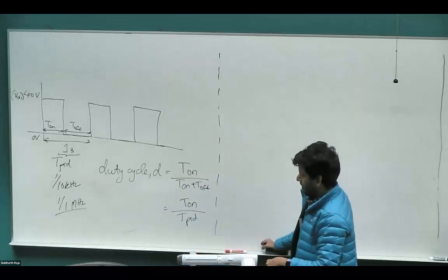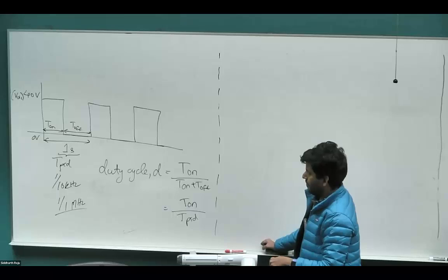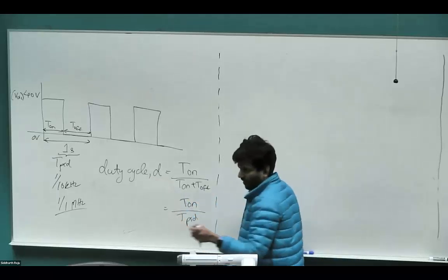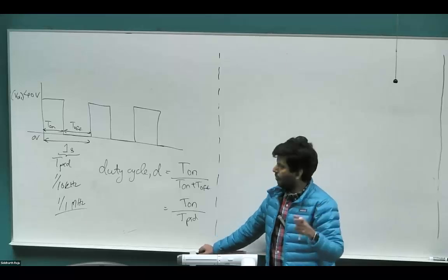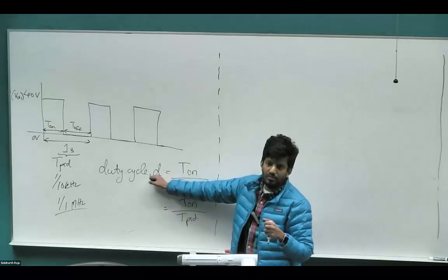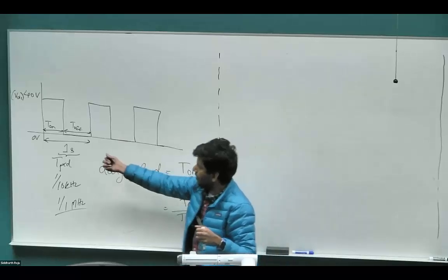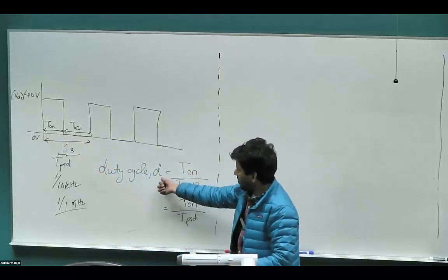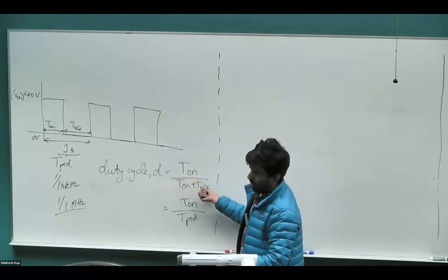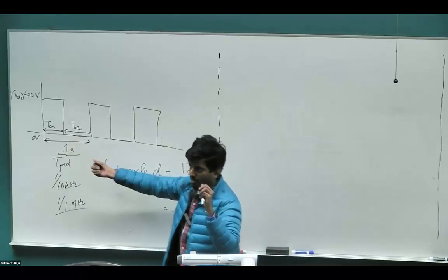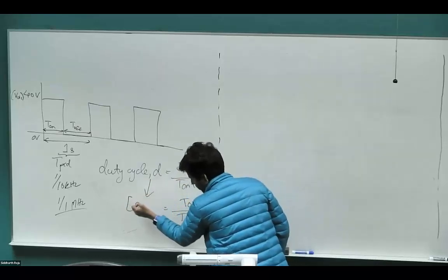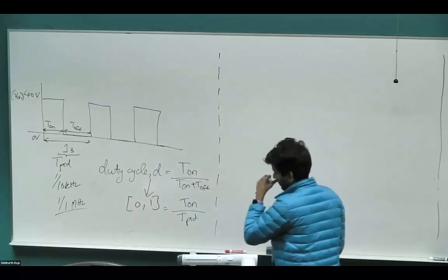So it's quite small, the time period in a real world situation, right? When I say I'm changing the duty cycle, when I was increasing the slider, what I was doing was increasing this duty cycle. When the duty cycle is 0, the on time period is 0, it's fully off, you don't see anything. When the duty cycle is 1, it's fully on, there is no off. So you see the lamp fully on without any flicker. So duty cycle has a range going from 0 to 1.